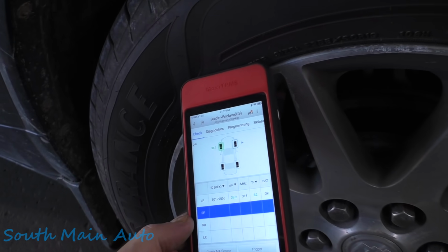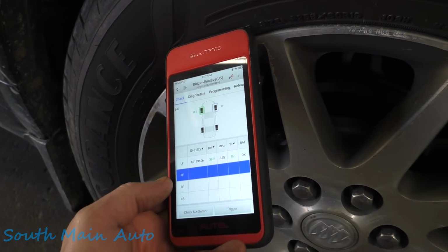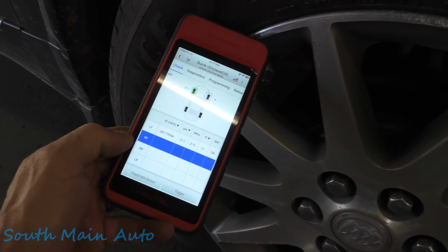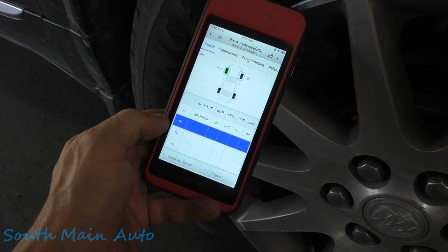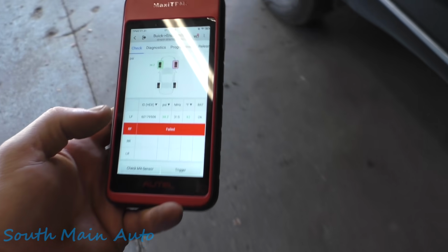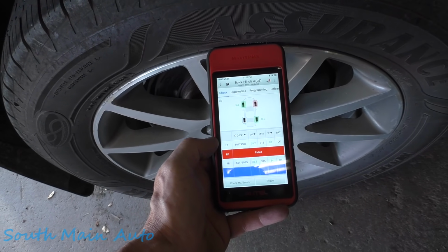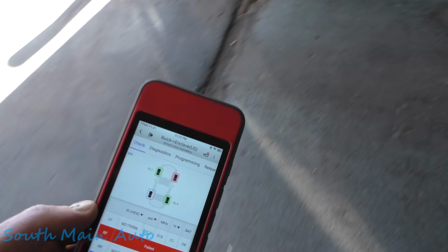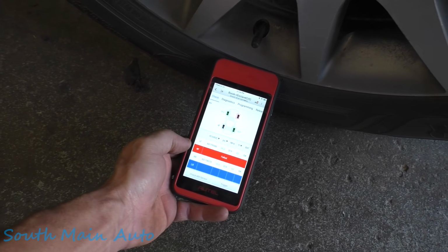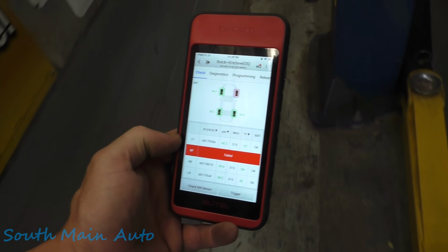And as I told you guys, sometimes that doesn't always stand true, because if somebody didn't program them when they rotated the tires, then where the car thinks the right front is, it isn't. But in this case, it looks like it probably is, because this should have triggered by now. I'll let it go till it times out. All right, we got the big fail on that one. So come back here, we'll double check all of them. Usually they trigger pretty quickly. And then all we've got left is the left rear. Trigger that one. Okay, so indeed this one is correct. The right front has failed.